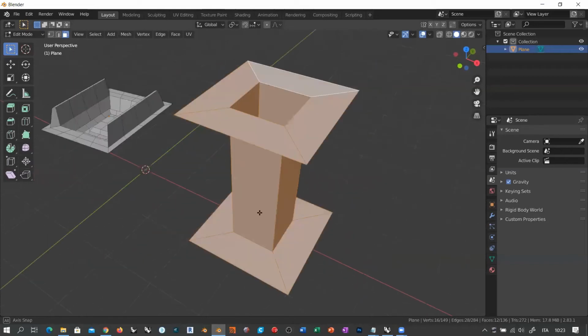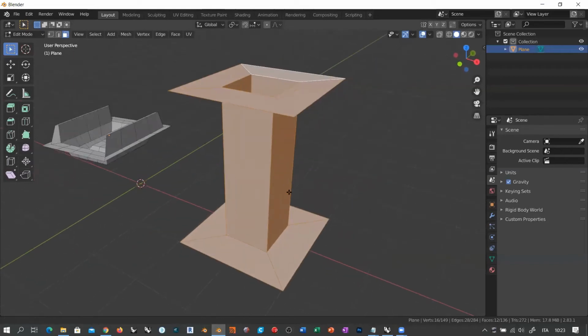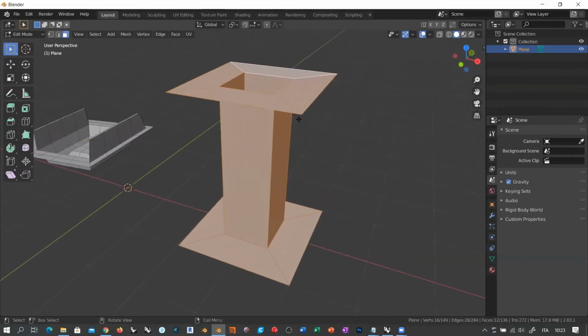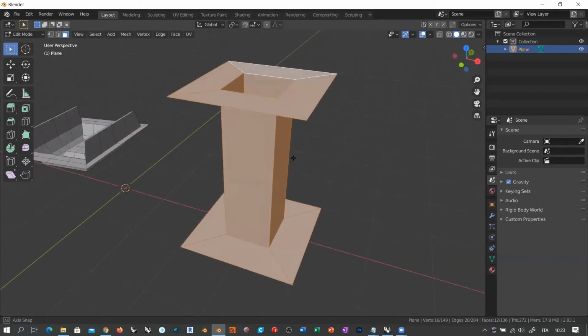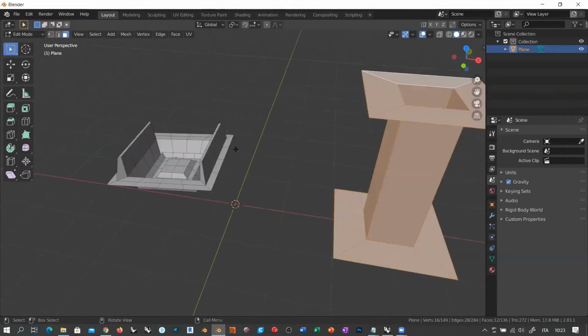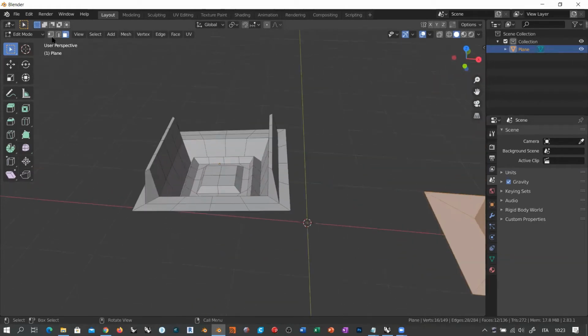The interesting thing of this regular topology is that if you create it in a very low poly fashion, like in this case, whatever type of subdivision you apply to this object, it will maintain the actual topological regularity. Okay, so for example, let's get rid of this because we already know that this is not going to work because it has this kind of UV problems. So what I'm going to do, I'm going to switch to vertex selection and then select these vertices here.